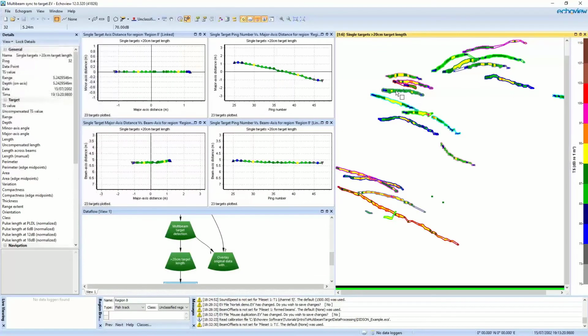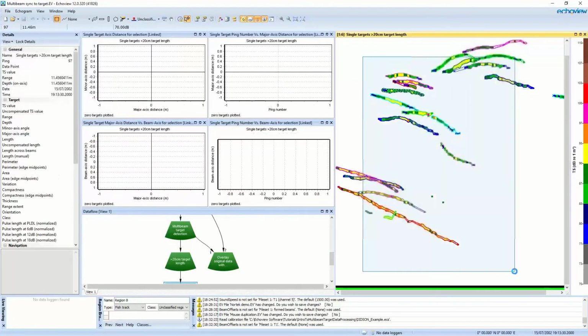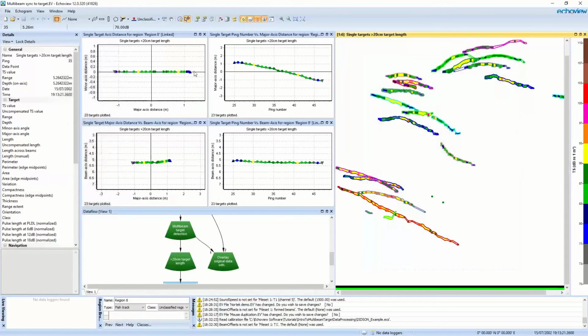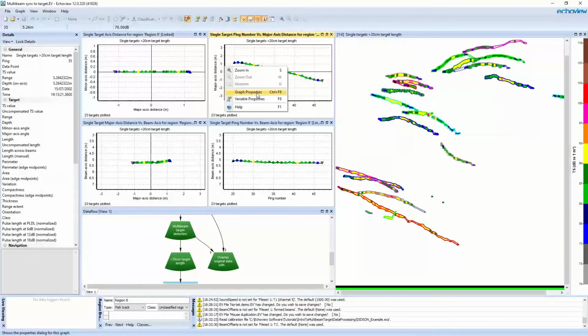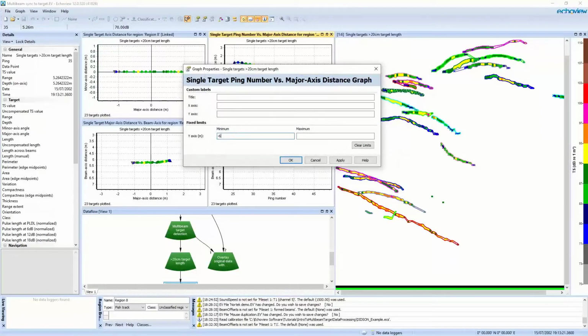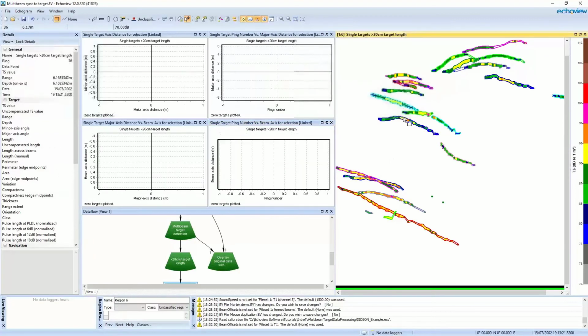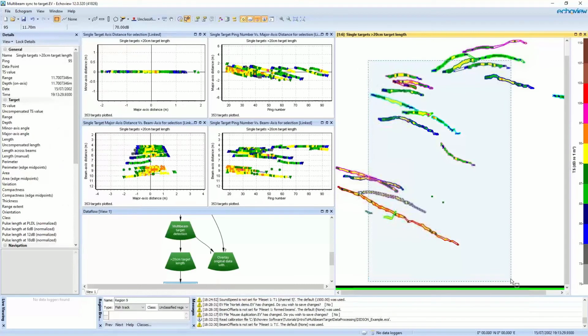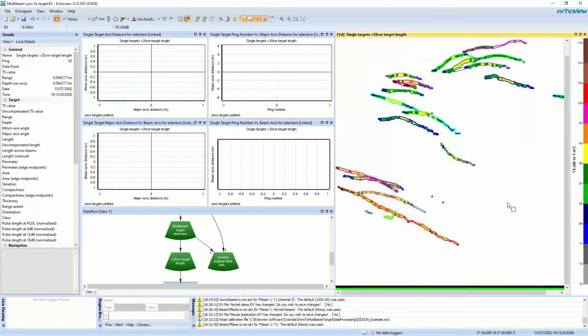And similarly to before, it's a bit hard to compare when these scales are changing, different selections or regions. So again, this would be another example of a time that it would be useful to lock some minimum and maximum values so that when we're comparing, we get a better understanding of the differences between these tracks. Echoview has a lot of tools for synchronization, and they're really useful to use regularly just to make it easier to understand your data.